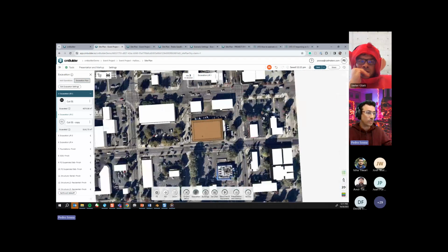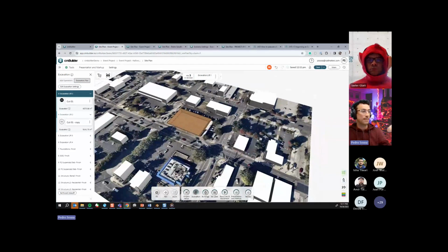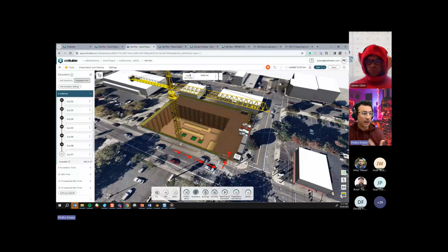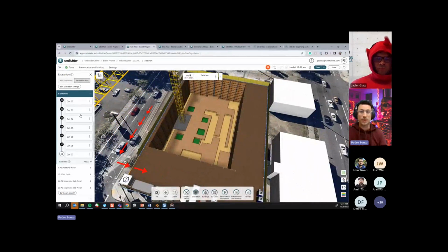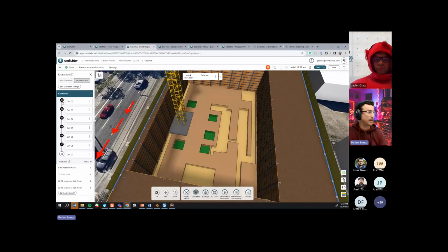Cool. So this is a quick way for you to investigate what might be causing a geometry to look a little bit weird. But there is also another thing that I'm not sure everyone knows about. When you have an excavation milestone like this one, where you have several steps, and let's say that I created something over here that made my geometry broken, I could simply create over here and see all the intermediate steps of that excavation, right? So just a reminder that the excavation tool works on a Boolean operation.